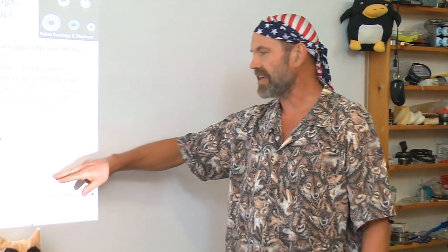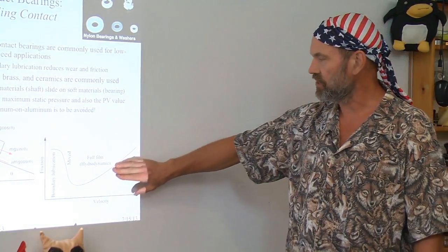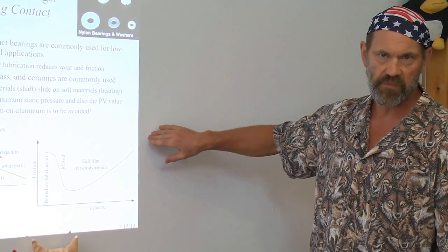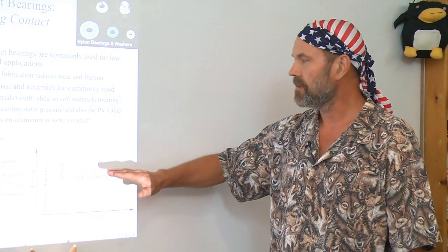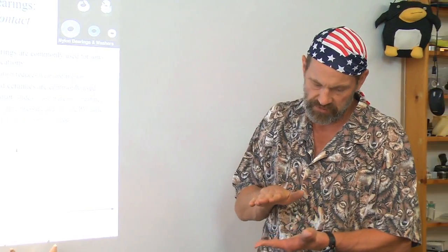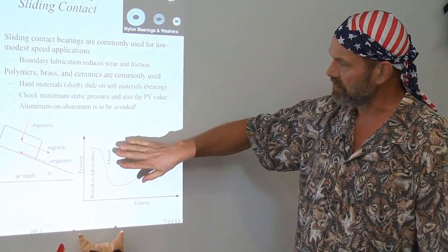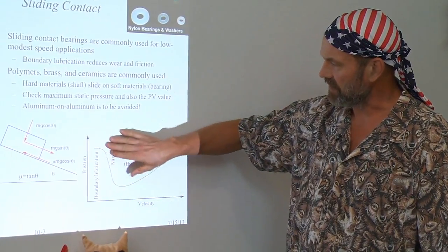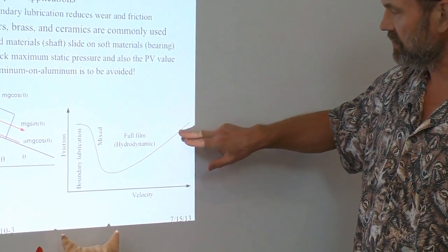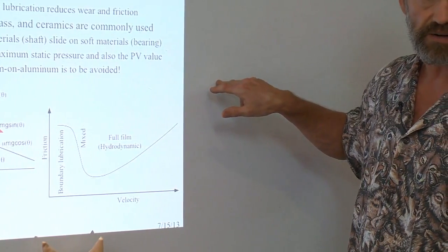You keep running faster speeds and the apparent friction goes up, because you're shearing the fluid and now you're getting more hydrodynamic drag. How is that related to, quote, coefficient of friction? That really should have nothing to do with the applied load. The applied load causing a classic Coulomb type friction really comes in more on the boundary layer. But remember, this just tells you that you have a nonlinear friction effect, something to be aware of with all bearings.